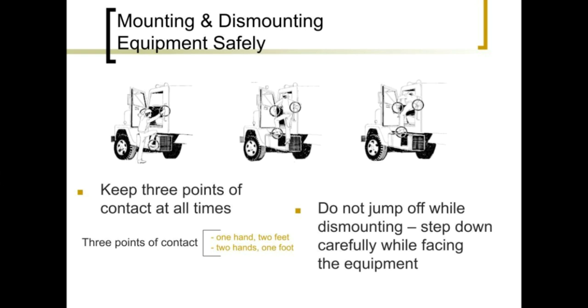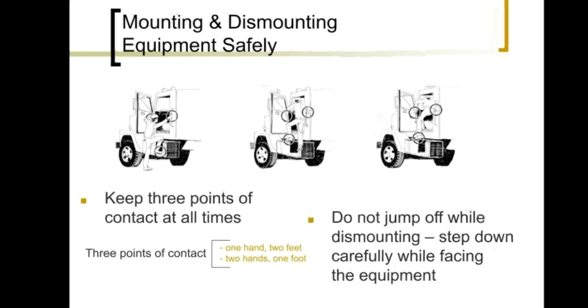Keep 3 points of contact at all times. 3 points of contact include 1 hand and 2 feet, or 2 hands and 1 foot. Do not jump off while dismounting. Step down carefully while facing the equipment.